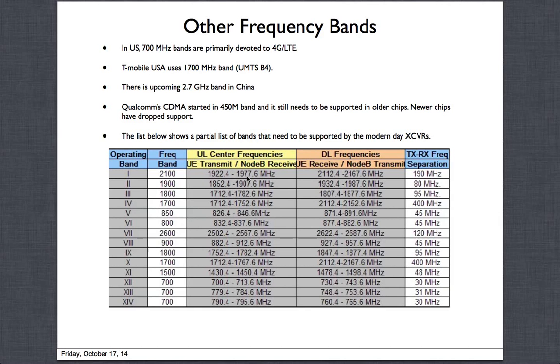and within this is a band. It has many channels. There will be many carriers who have won the auction of many channels, and their subscribers will be transmitting in this band if they're in band 1. So this is the transmit frequency, and this is the receive frequency. And the duplexer, as I showed you in the picture previously, has a filter for this transmit and a filter for this receive, implemented for the various reasons we talked about earlier in our lecture. And if you look at the transmit and receive, the separation is 190 megahertz.